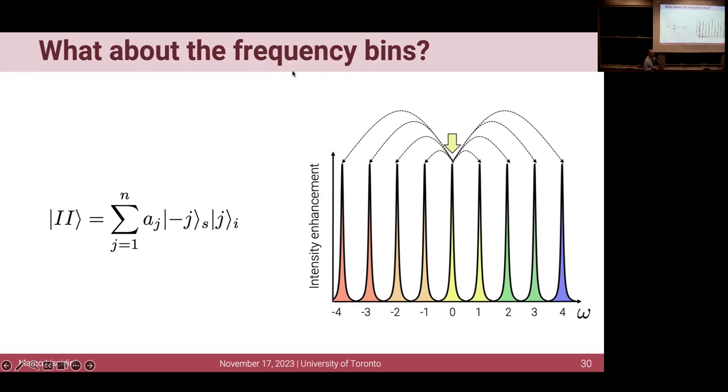Yes? I take it those numbers were for reasonable experimental parameters in terms of how well these rings could be made? Actually, these are the real numbers that have been measured. And what kind of finesse do you have for that cavity? The finesse. Okay, so let me. Yeah, I said the Q is 8,000, at 1550. That's enough. Yeah, 8,000 of Q.